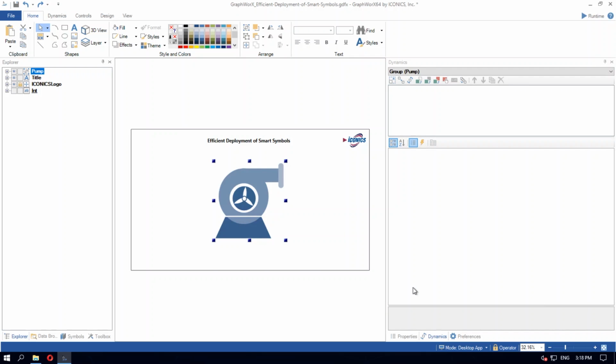This is not a bad thing in and of itself. However, if we need 100, 1,000, 100,000 pump graphics, changing four properties for each pump is time-consuming. To merge the four properties into one smart property, we will check the Optimize Hierarchical Data Sources checkbox.